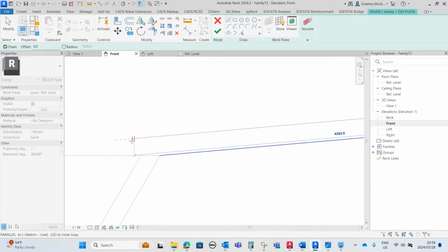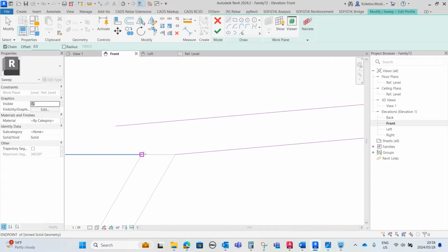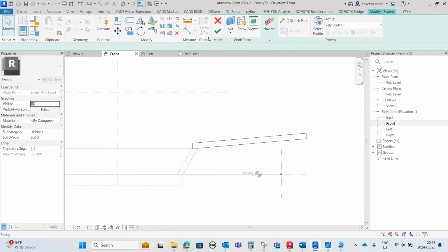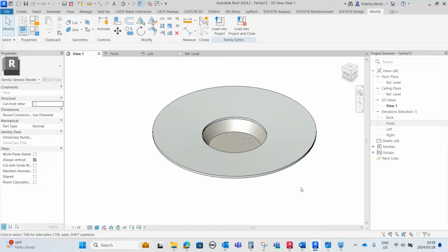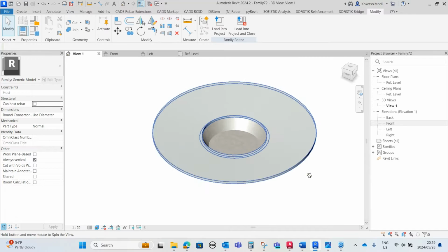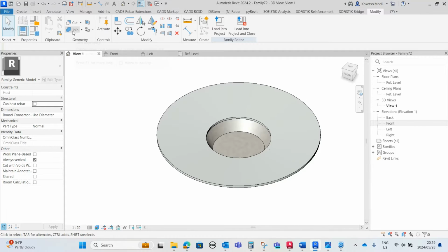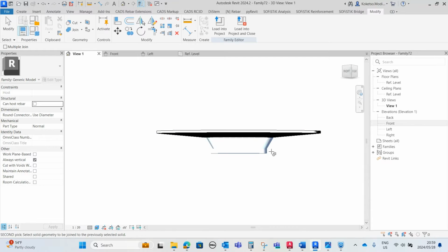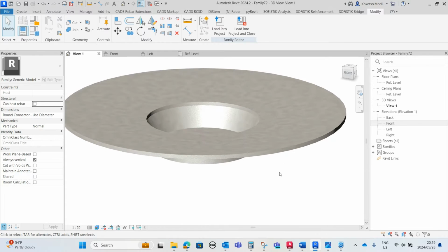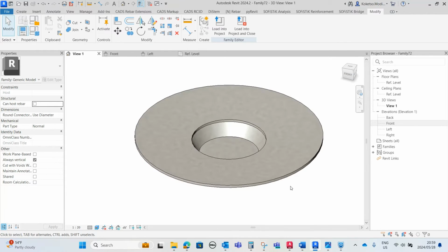And then I'm just gonna bring it diagonally like this, and then press escape, and then I'm gonna draw a vertical line like this so that it meets this diagonal line. And then I'm gonna say trim and extend. Then I'm gonna do the same thing here, just connect it like that and say finish edit mode, go to a 3D view, and this is what we have. Perfect. Now, obviously, I'm gonna say join and then select the sludge well, and then I'm gonna join it with the concrete floor, and then it's gonna change its material. So this is basically what we have.